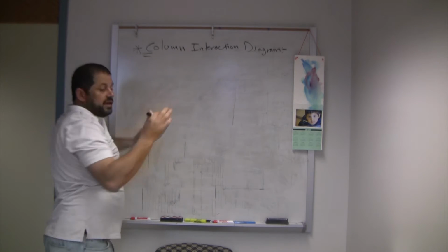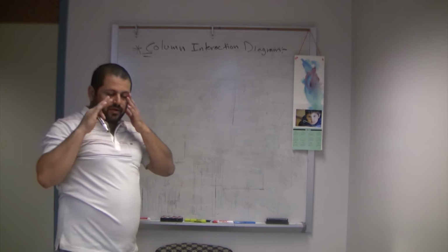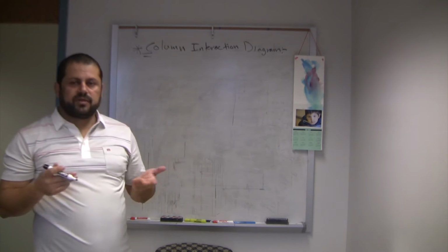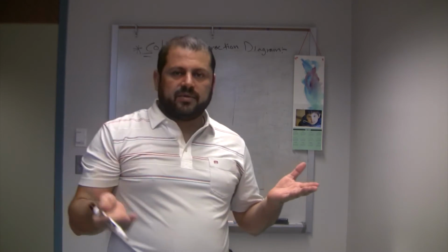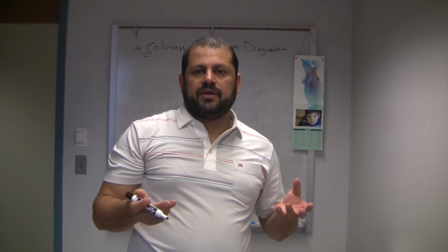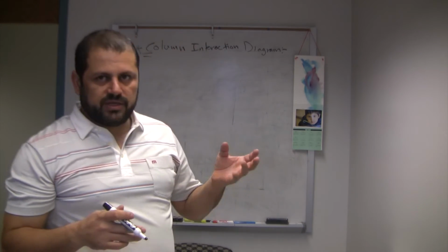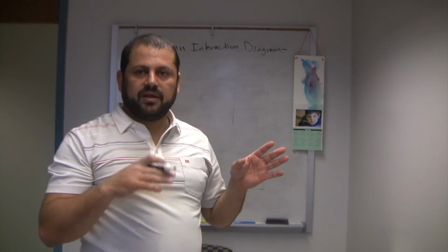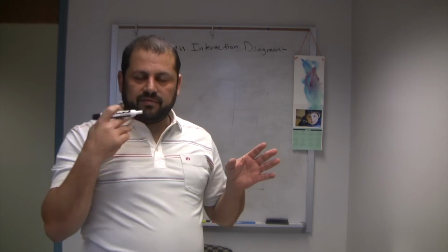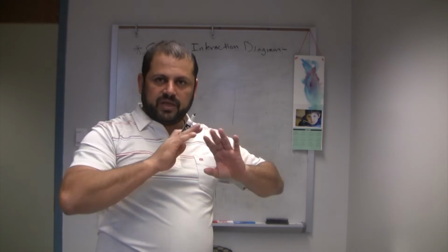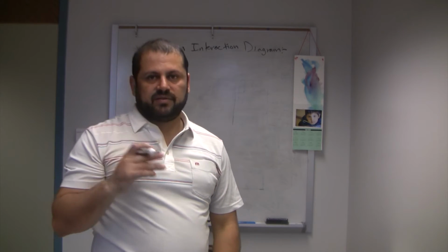So again, in the case when you have pure axial load, if we are saying what's the nominal capacity of the column, we are talking about Pn. When we say the design capacity of the column, it's phi Pn. So if it's a tied column, the phi factor is 0.65. If it's a spirally reinforced column, meaning the ties are a continuous spiral, the phi factor is 0.75. And we gave the equations and we gave an example in the previous lecture.